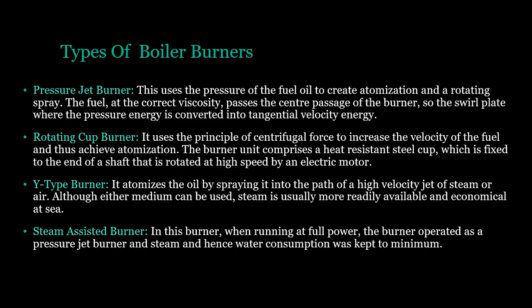Y-type burner: it atomizes the oil by spraying it into the path of a high-velocity jet of steam or air. Although either medium can be used, steam is usually more readily available and economical at sea. Steam-assisted burner: in this burner, when running at full power, the burner operates as a pressure jet burner, and steam and hence water consumption is kept to a minimum.